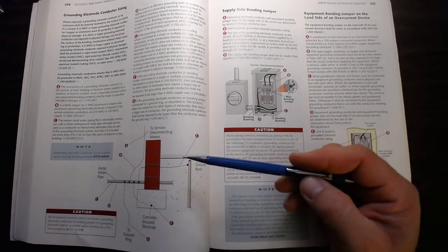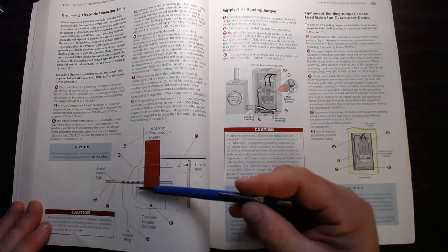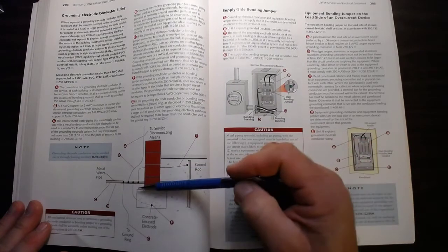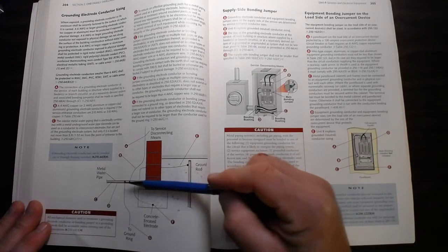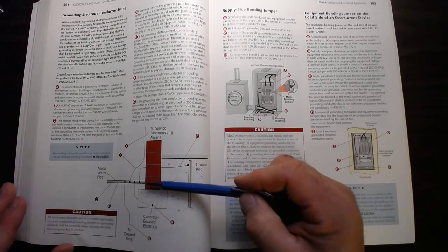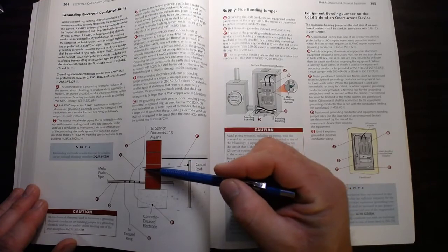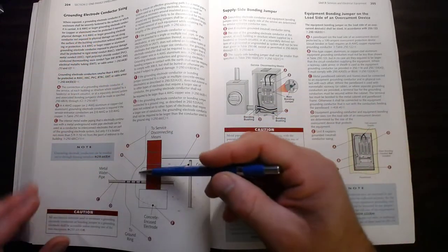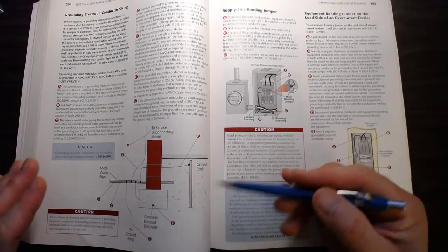Establishing the grounding electrode system, you're going to see that everything needs to connect to that grounding electrode system. Concrete encasement to metal water pipe, ground rod to the metal water pipe. Now they're using the metal water pipe here as a busing, but ideally you wouldn't do this. Now again, we're talking about dwellings, so this is probably going to be the easiest way to do it. But they do make flat bus bar, and then you would drill and tap holes in it, and you would bolt all of these to that connection, and you would do that in commercial and industrial for sure.